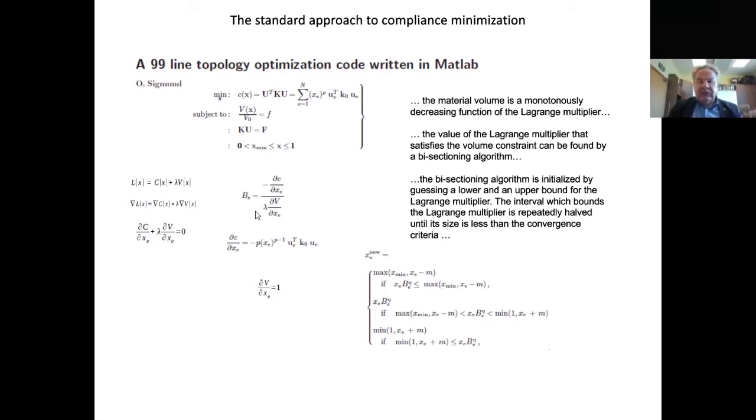And the main assumption is like this: if the element has higher energy, so the compliance is higher, so we want to make this element stiffer. If there is no energy, or the energy is low, so we want to make this element less stiff. And everything is possible to compute. This is the assumption that